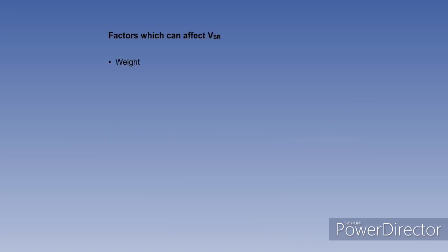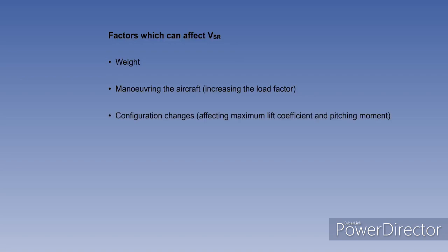There are several factors that can affect the value of VSR. They are weight, maneuvering the aircraft, increasing the load factor, configuration changes, affecting maximum lift coefficient and pitching moment, engine thrust or propeller slipstream, Mach number, wing contamination, and heavy rain. We shall now examine how these changes work.